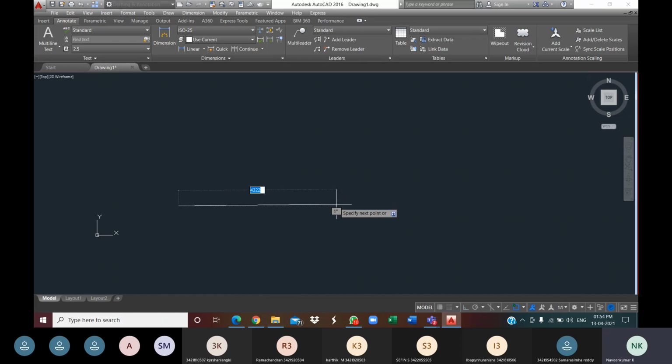If you don't want it like this, if your ortho option is off, you can have angular lines. Angular line in the sense you can orient your line in different angles. So whenever you require, you click on the ortho on. Whenever it is not needed, you can turn the ortho off. Okay, so as of now I am on the ortho.